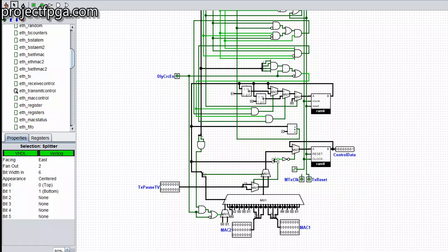So that is basically what this circuitry here is doing. It takes the LSB of our byte counter, which we know already goes on and off, 0 and 1, 0 and 1. No matter what value is counting, it's always going 0 and 1, 0 and 1. And it actually uses this NOT gate because it doesn't want to count 0. It wants to count when it's 1. So the first count, 0, doesn't take anything. Then the next count, 1. At that point, it has already counted here, so it has 2 nibbles at that time.